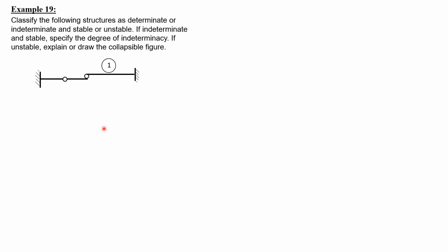How about vertical? If you put a load here, it will transmit vertical load here, but there is vertical constraint here, so it will not move. It will not also rotate. Rotation is prevented also because of the available constraint.